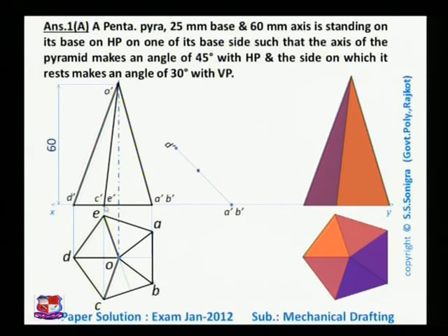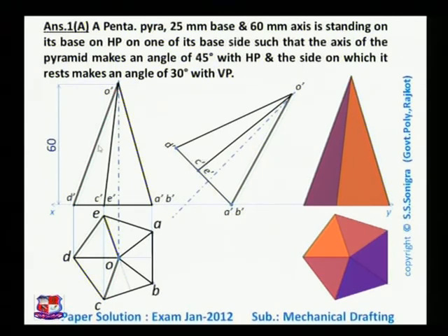Now transfer another point. Here is point C dash, E dash, that would be here at this distance. So measure this distance, put it over here, and that is point C dash and E dash. Then find out the position of apex point O dash by taking an arc. A dash, O dash is the radius and D dash, O dash is the radius. Cut that arc over here. So here apex point O dash would be there, and join them with a straight line, and join C dash, E dash with apex point O dash like this, and this is the axis of this solid. So till now we have just redrawn this front view at an angle of 45 degree with the XY line. This angle is 45 degree, hence this angle will also be 45 degree.